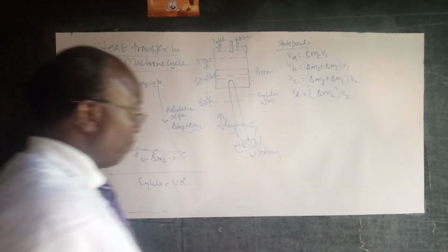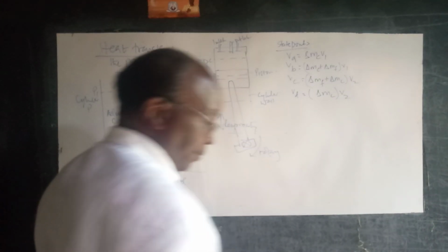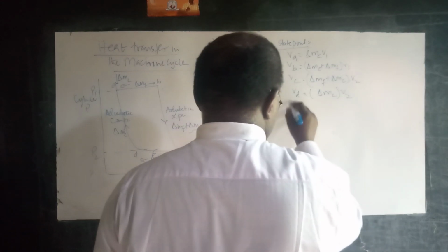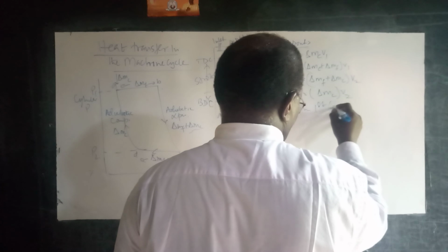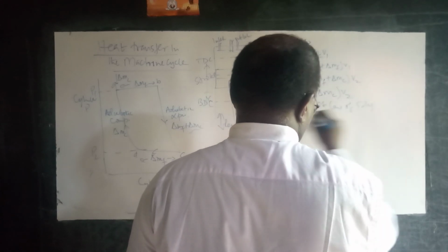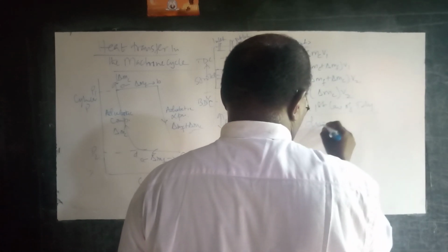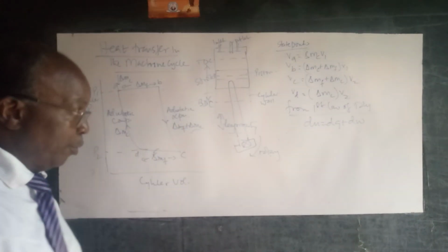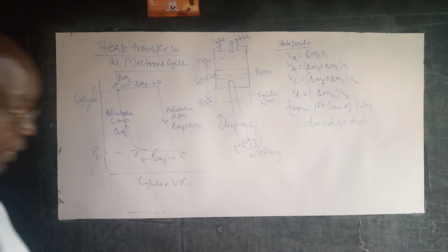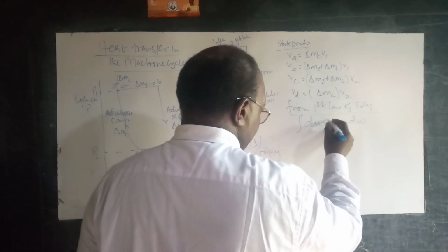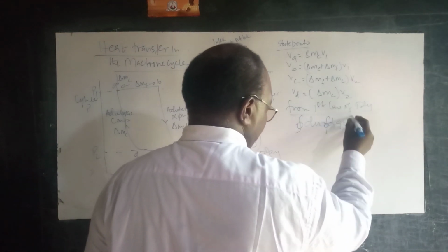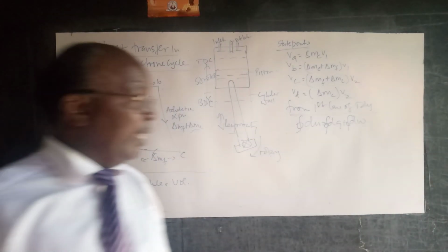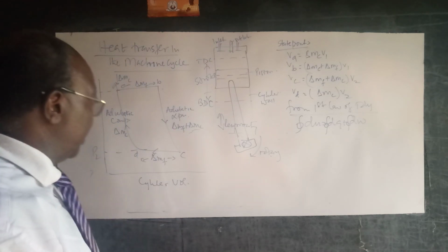Now, if we take the overall expression in this system using the first law of thermodynamics, we know that du is equal to dq plus dw. So if you integrate over the whole cycle, remember, when we talk of these cyclic integrals, we say they consist of four line integrals for this particular case.